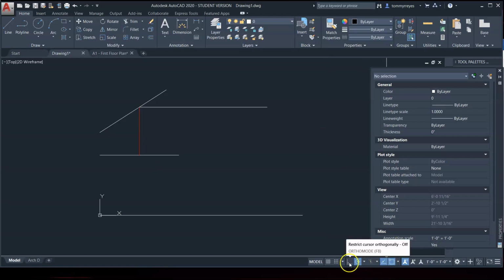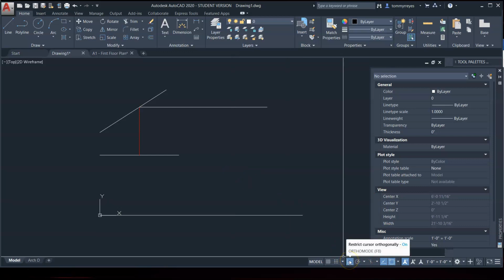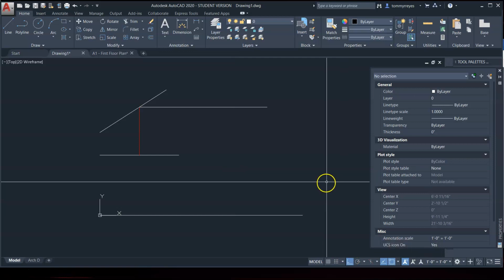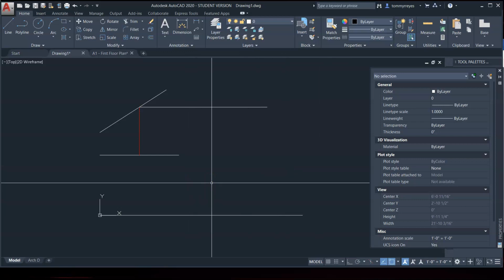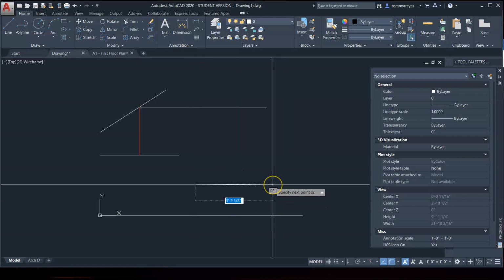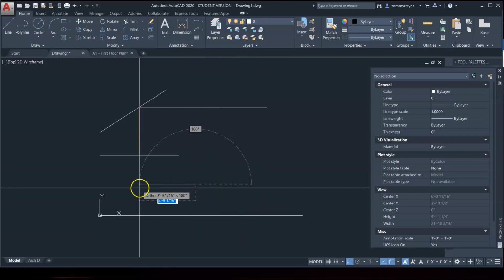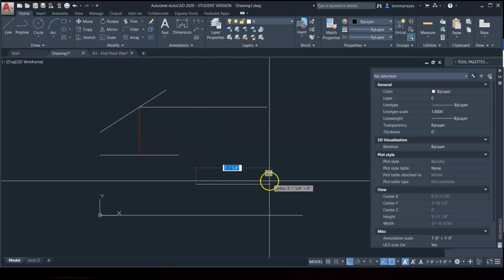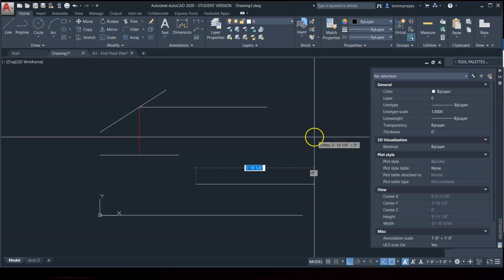But drawing floor plans, I find that ortho mode is the best mode. I know it says F8, or you could hit Control L, or on a Mac you could hit Command L. And now I'm in ortho mode. So line, oop. And ortho just means 90 degrees. I can only draw lines in 90 degrees. And if you're drafting a floor plan and there's nothing but rectangles, well, you only need 90-degree increments. You don't need 30 or 15 degrees.